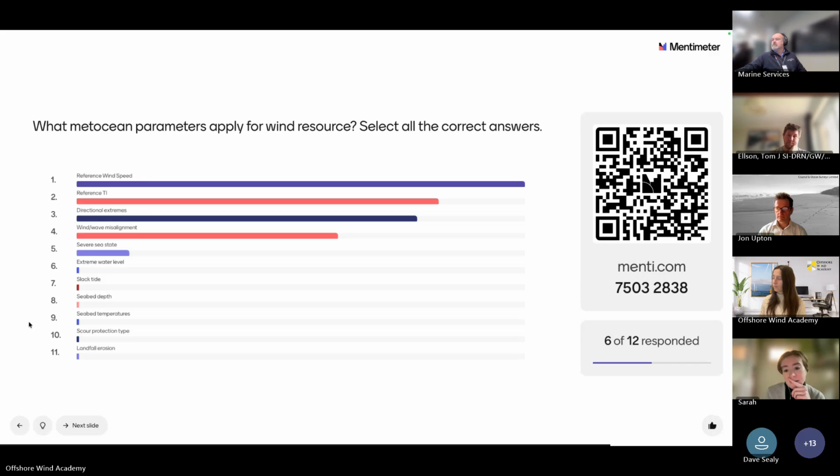All right. So severe seas is a really interesting one because indeed you do have to have a tip clearance with the ocean surface, and this is for boats transiting. It's a parameter or a governmental requirement, I think. So indeed, understanding the severe sea state is important. Well, I guess I'm not going to be too picky here. Wind resource analysts, of course, are taking this into account when they're selecting your turbine, selecting the turbine height, the tower height itself to maintain that air gap. And of course, that is always going to influence the aerodynamics, although I don't believe our models really get to that level of refinement that we use in the industry.